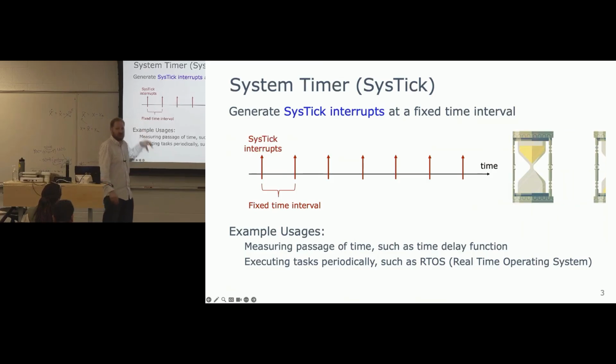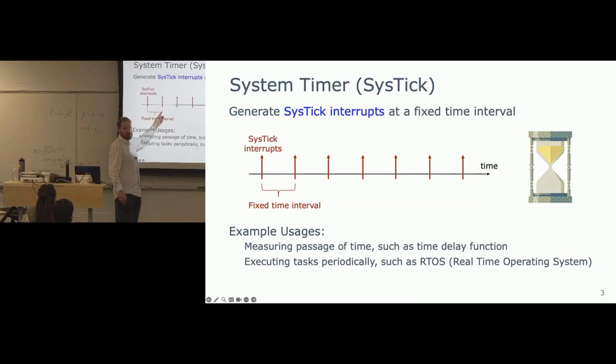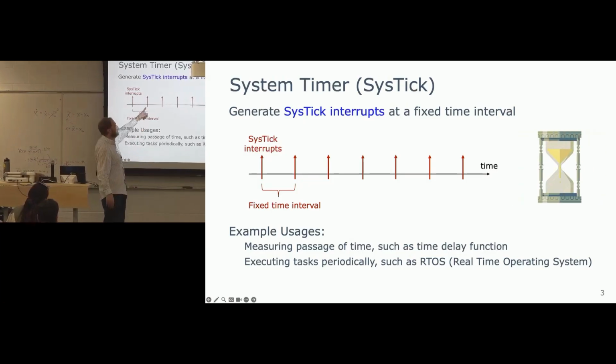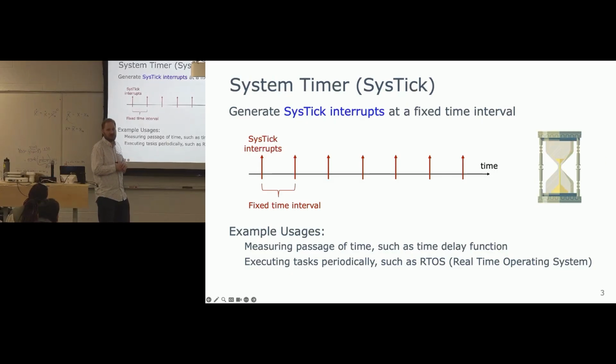So you could just say, I don't really care, right? I'm hitting all my stuff. I have a light workload. I'll just go idle for a while. Another thing to do oftentimes, depending on your programs, when you're done, you might go into a low power mode to save power. And then you're just going to wait till you wake up, and then you're going to do some other task. And so I've written things for little sensors where you do something like SysTick, but the interval might be 30 seconds. And you wake up, you do a little bit of task, and you go back to sleep, and then you're waiting for an interrupt from a sensor or something to wake you up to do a task.